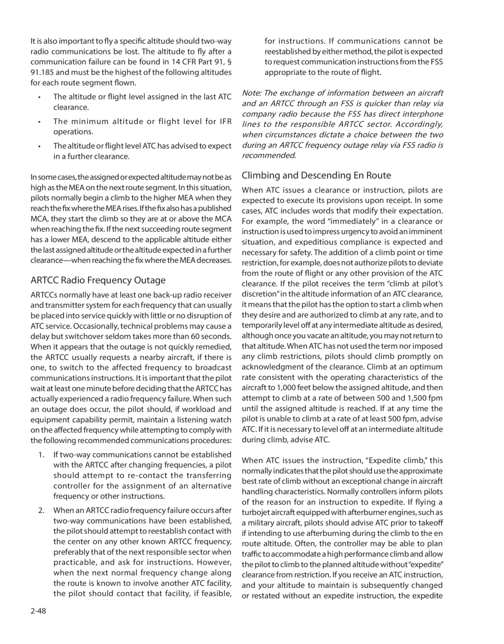Note, the exchange of information between an aircraft and an ARC through an FSS is quicker than relay via company radio because the FSS has direct interphone lines to the responsible ARC sector. Accordingly, when circumstances dictate a choice between the two during an ARC frequency outage, relay via FSS radio is recommended. Climbing and descending en route.